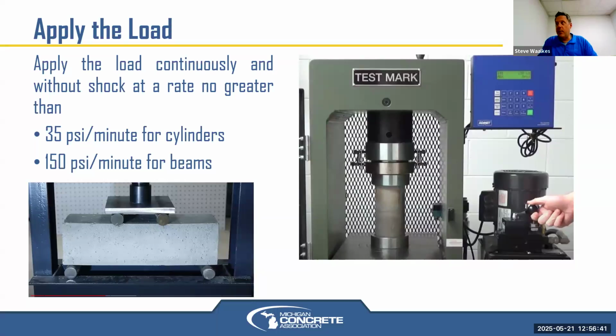Or is it exterior flat work where you want to touch it as little as possible and just strike off and bull float and texture, broom texture or whatever, and then you didn't do a lot of finishing to that surface. It's the exact same mix, but different levels of finishing can have a different rebound hammer or Schmidt hammer number or result. So it's a rule of thumb type of thing.